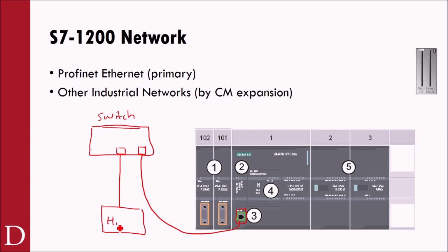So you've got your PLC and your HMI, and then an additional Ethernet port that will plug in to your PC. So over here you'll have your PC with your programming software, and you'll actually be writing the code that you're going to use on the PLC. So the nice thing is no more hot swapping cables, no more plugging in a 232 cable here, moving it over to here, swapping it out with a different cable for the HMI. All of that's going to be controlled over that Ethernet switch.